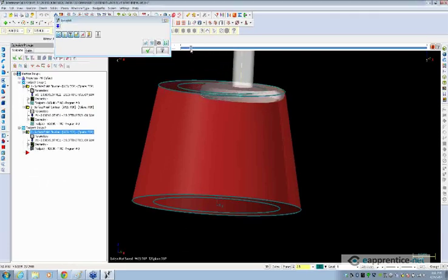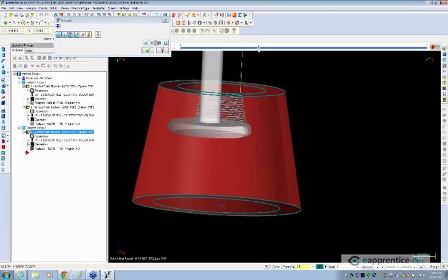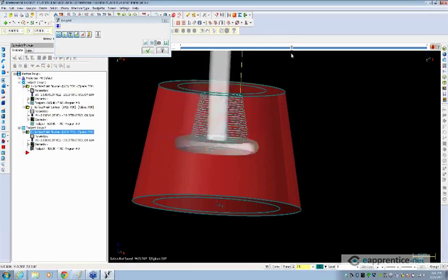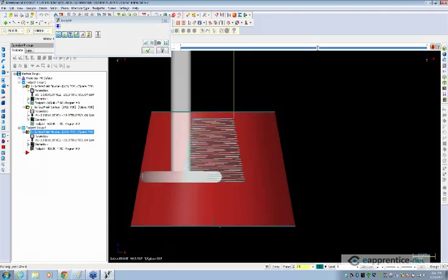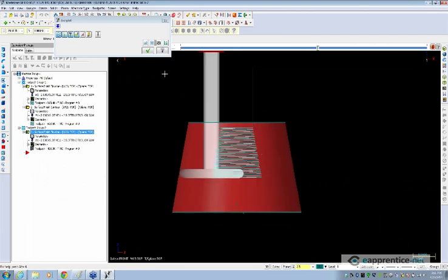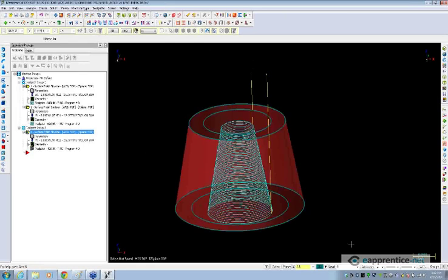Okay, so now this toolpath is looking really nice. You know, we're getting some good motion. You know, we can adjust the step over, change all those parameters. But the motion itself is looking exactly what we want. We're taking this slotting mill, full radius, and we're driving it, you know, tangent to the surface that we're cutting. Okay, great. Everything's good except for this approach and retract.